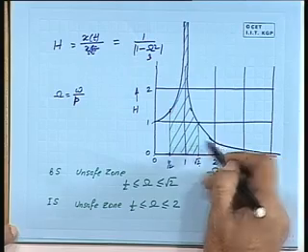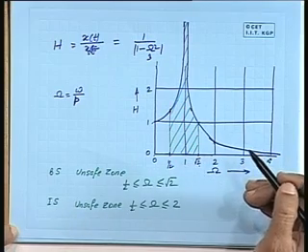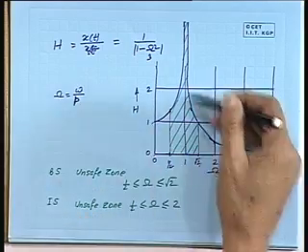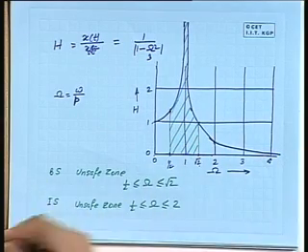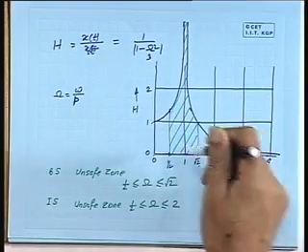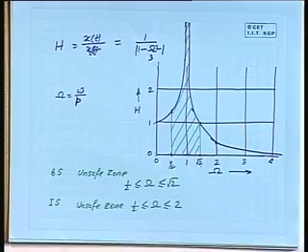So, it becomes 2, but actually speaking, when the ratio is coming down, it becomes safer, and what you will find is that at a high frequency a calm situation prevails. At low RPM or low frequency, low excitation, there is every chance that it will blow up, but at a higher excitation a quieter situation will be available.